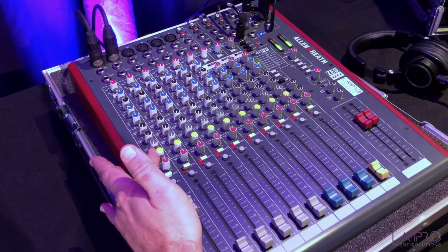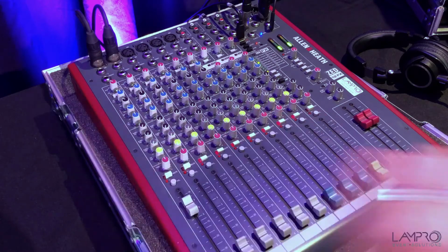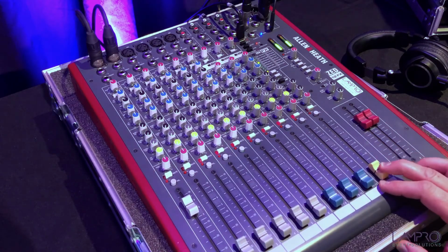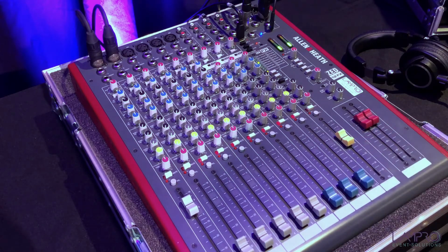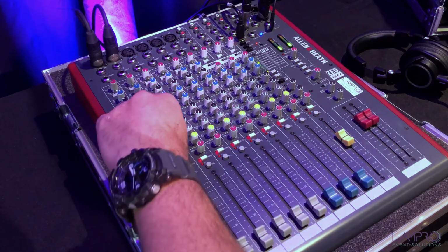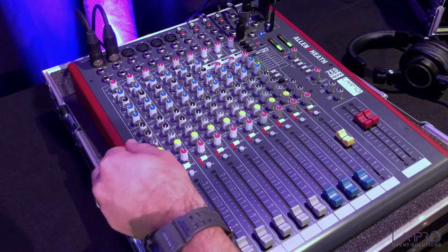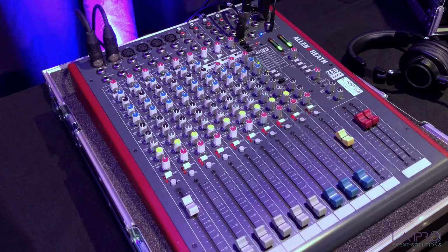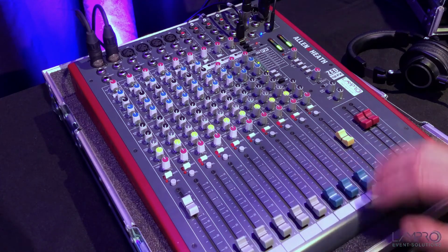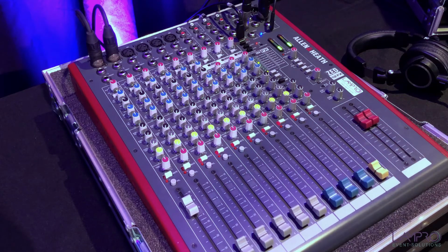And if I actually open the post aux on channel 1 where my microphone has been patched, and I open the effects master, you'll be able to hear the effects being sent to the recording. If the effects post auxiliary is closed, it won't send anything. If it's opened again, you'll hear the effect. But if the aux master is also closed, you won't hear any effect.